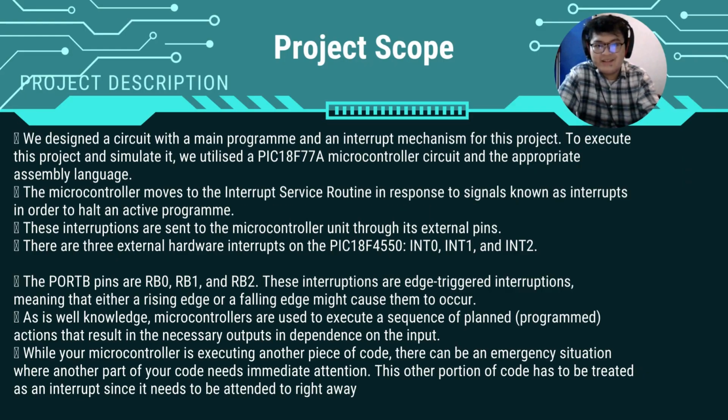The main goal of this project is to teach students to design electrical circuits with software, which is Proteus, depending on the specification given in the project instruction. So this is the project description that we found. For the first one, we design a circuit with a main program and an interrupt mechanism. To execute and simulate this project, we utilize a PIC18F4550 microcontroller circuit and the appropriate assembly language.